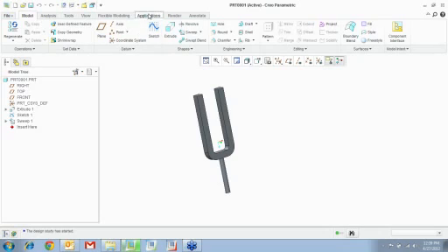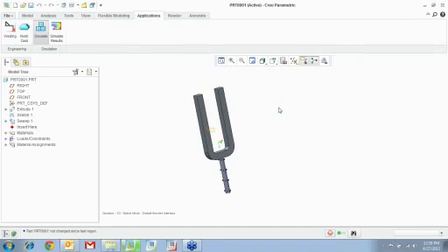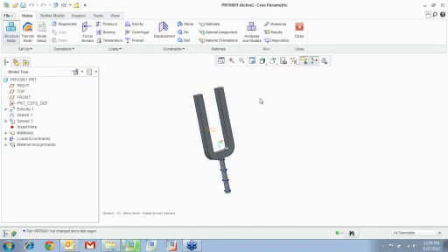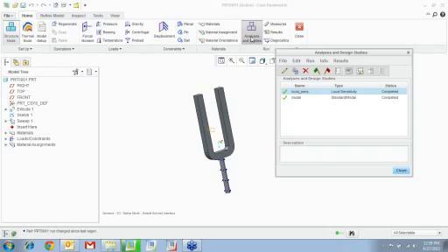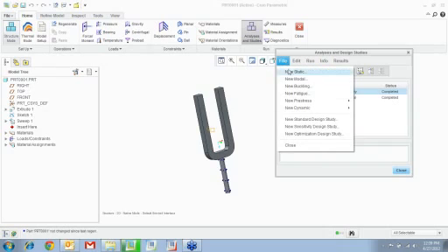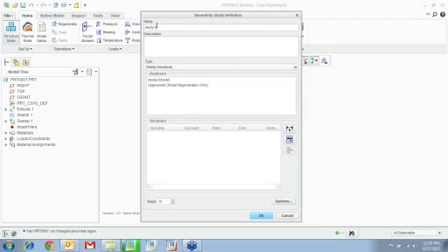Now let's run something called a global sensitivity. In a global sensitivity, you give it a range. So analysis, file, sensitivity study, and here I'm going to say global. I'm going to pick that analysis as a base analysis.